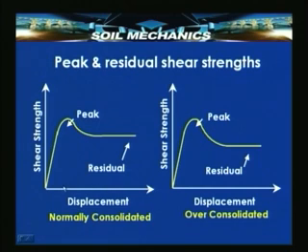If you take a normally consolidated soil, you will have a shear strength versus displacement curve, which will be something like this, which shows a peak, and then it comes down and shows a residual value. With large displacements, the value goes beyond the peak and then comes down and remains almost constant. So is the case with over consolidated clays also.